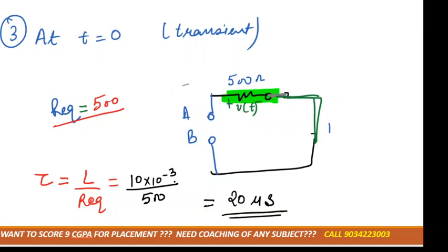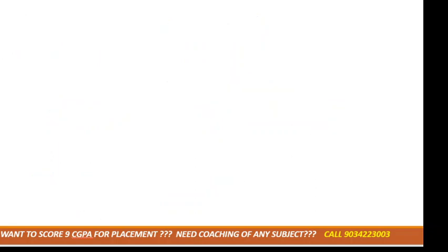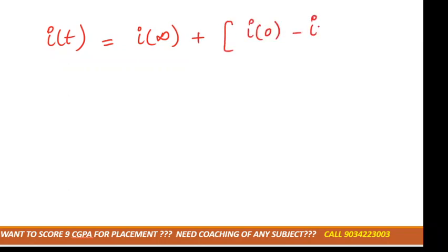20 microsecond. Second, its unit is second. So we can simply put it in the I(t) equation, that is I of infinity plus I of 0 minus I of infinity times e raised to power minus t by tau. I of infinity, how much did we get?